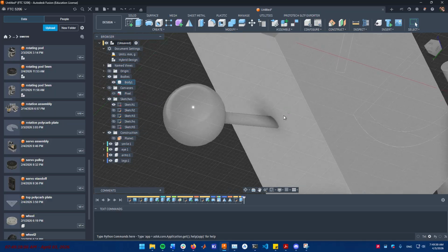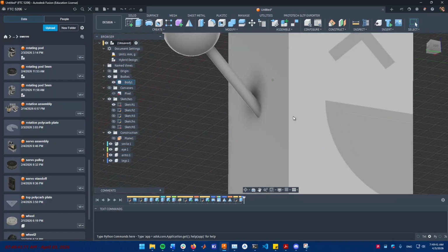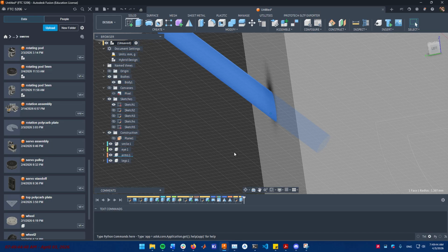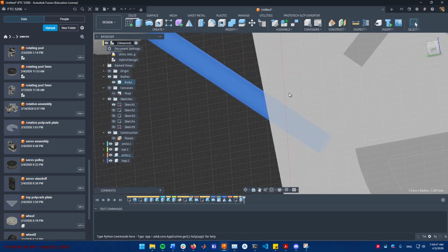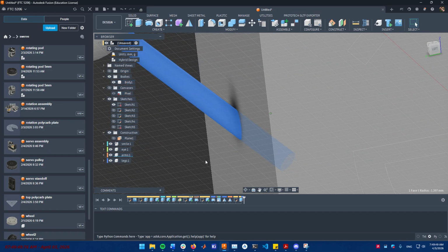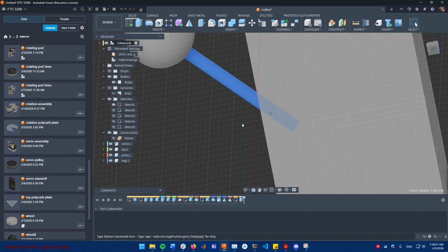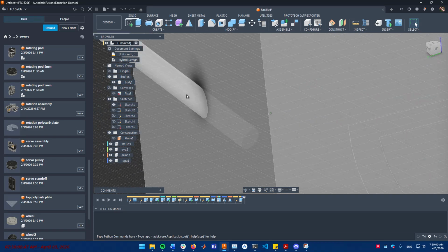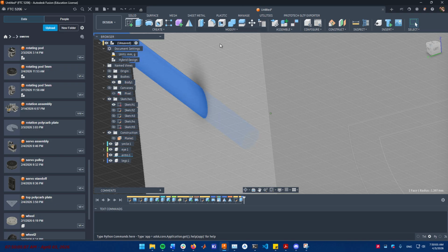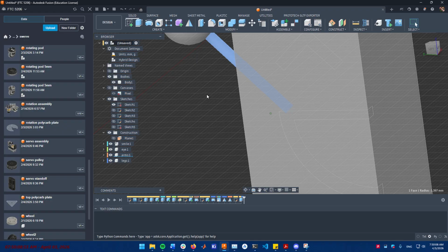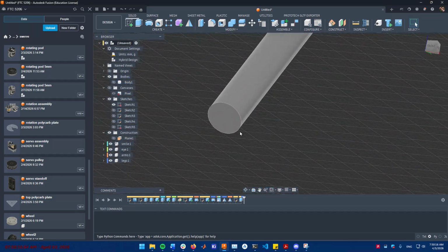But you may wonder, how are we going to create the hole in this place, because the geometry is kind of wonky. So first, I feel like the most efficient way is to first extrude it based on this geometry here, and then add our standard offset. I don't know why my dog is so barky today, but we will proceed. So first, let us hide this body so that we can access this geometry here.